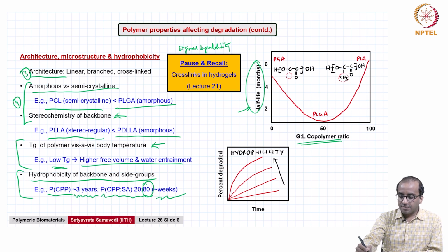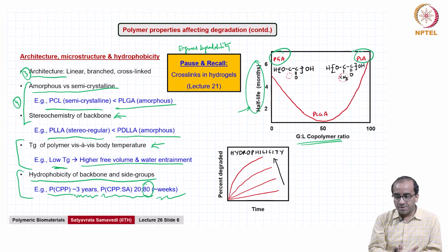Now, when you have the pure polymers PGA and PLLA, the primary difference you see is the presence of the methyl side group here, which is absent here, right? So, PGA and PLA will have a certain degradation rate, but once you start combining them in the copolymer PLGA in different ratios, the degradation rates consistently change, and that's largely because PLGA becomes amorphous.